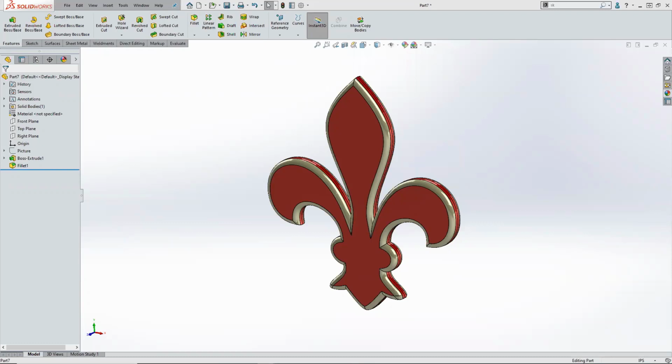That is probably the single best use of fit spline, because when you're running a cam and a follower, oftentimes the geometry or the modeling gets hung up on those individual surfaces and it stops. So fit spline gives it the opportunity to run smoothly all around the cam surface. You're absolutely right. It seemed to work, and it worked better than a path mate also. Yes, absolutely right.